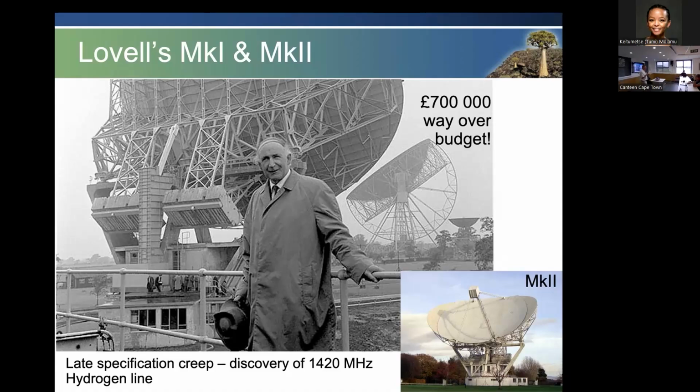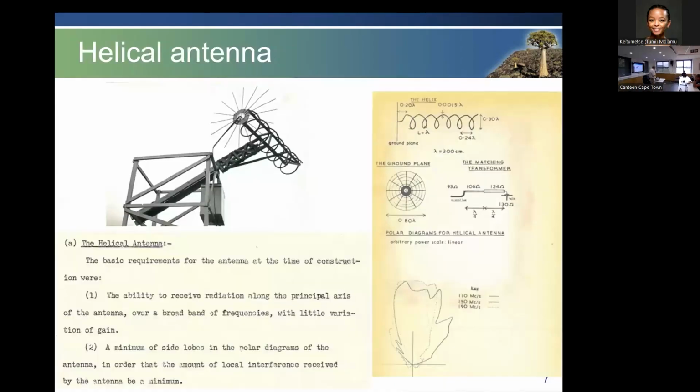So you could build it squatter. It would be lower to the ground. It would be cheaper. But as we'll see, the thing with an elliptical dish is you end up with an elliptical beam, and that's just a terrible, terrible thing to deal with. And so if you look carefully at the Mark II picture, you'll see that there's a surface on top of the elliptical surface, which is actually circular. And so the effective diameter is a lot less than it was.